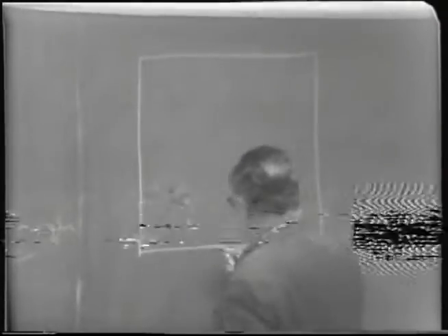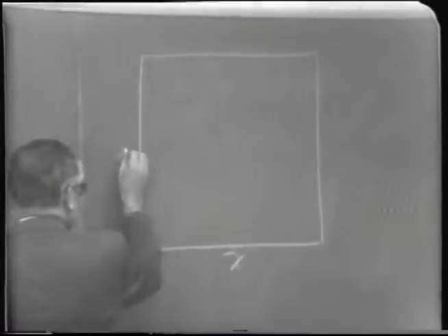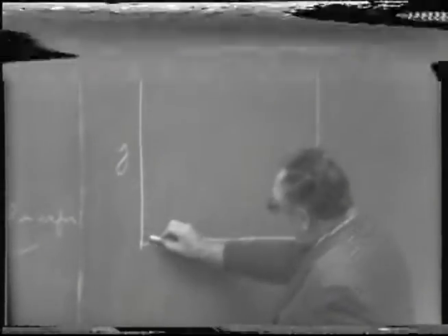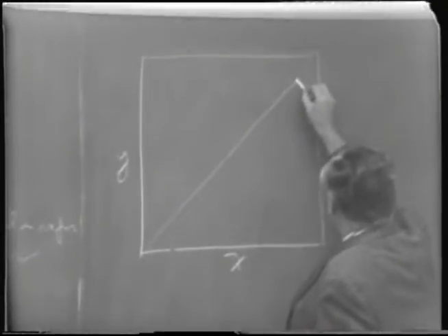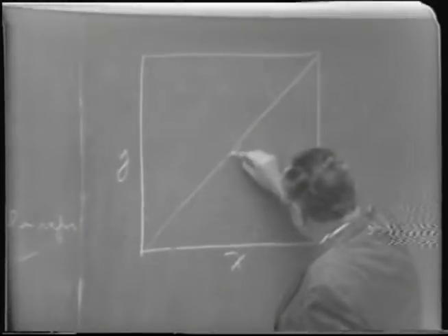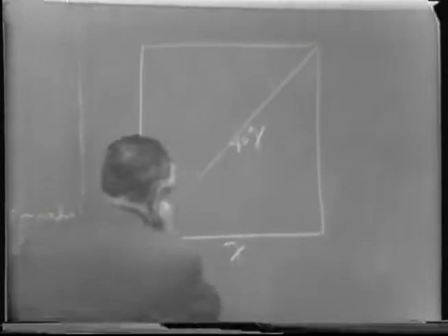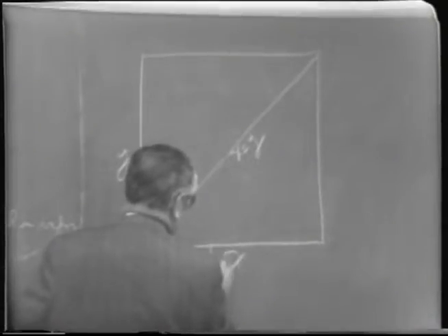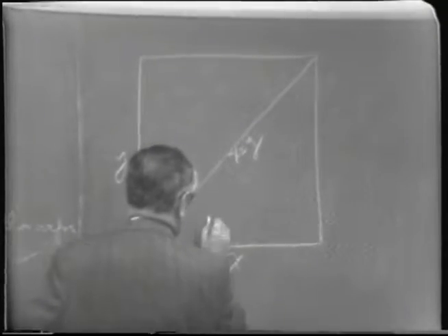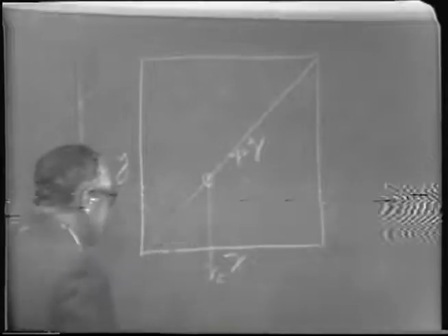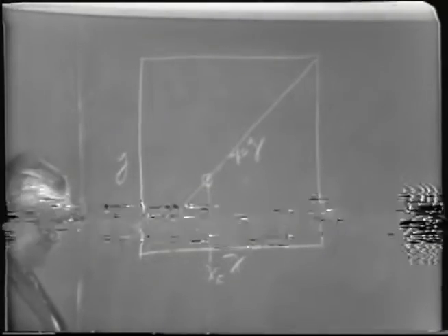Or in other words, if we want to draw an equilibrium curve plot here, where we plot x on the horizontal axis and y on the vertical, and invariably we draw a diagonal in here for reference purposes for x equal to y, this equation has to pass through this point on the diagonal where x is equal to y at a value of x sub f.